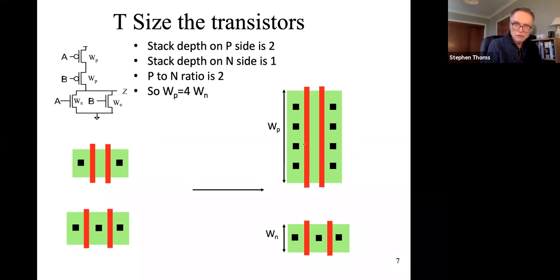It's not the length of the polysilicon, because the polysilicon, as you can see, extends beyond the opening in the field oxide, and that's because of what we were talking about last time, that we need to do the alignment, and it does need to extend. But these bits of gate which extend beyond the opening are on top of the field oxide, they have no direct influence on the device. The actual device is all in the green area. So that's the bit that gets multiplied in size by 4.